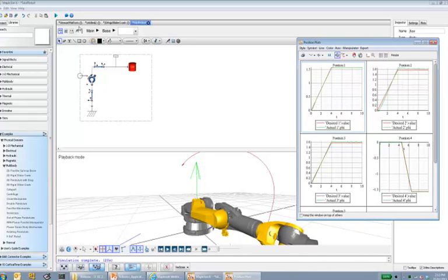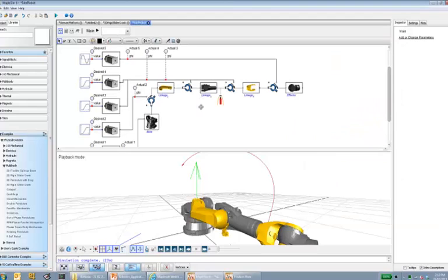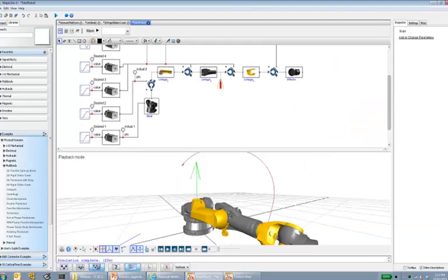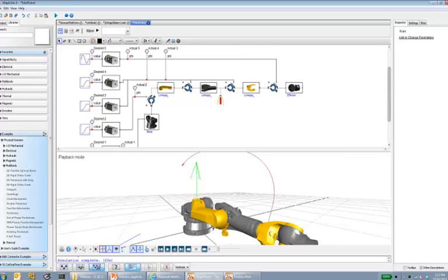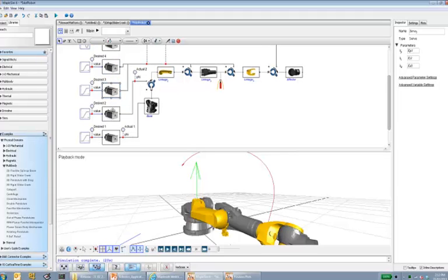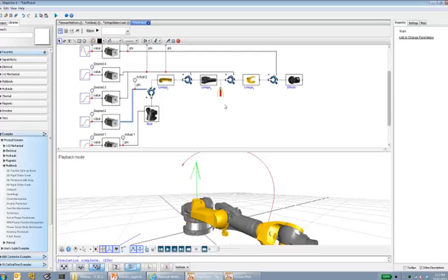And the rigid body links between each pair of revolute joints, as you can see, are connected to electrical motors. These identical subsystems represent electric motors, and the 1D rotational output of those motors is connected to the revolute joints. So this is what we mean by multi-domain environment.